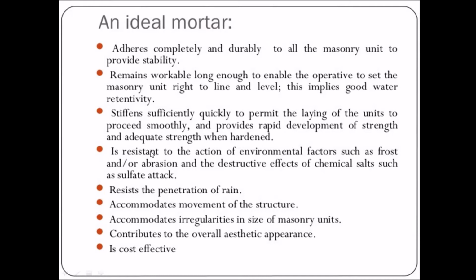An ideal mortar is resistant to the action of environmental factors such as frost and abrasion and destructive effects of chemical salts such as sulfate attack. It resists the penetration of rain. It accommodates movement of the structure. It accommodates irregularities in size of masonry units. It contributes to the overall aesthetic appearance. It is cost effective.